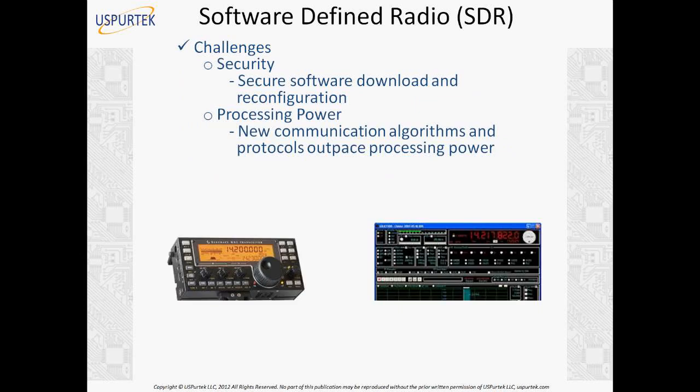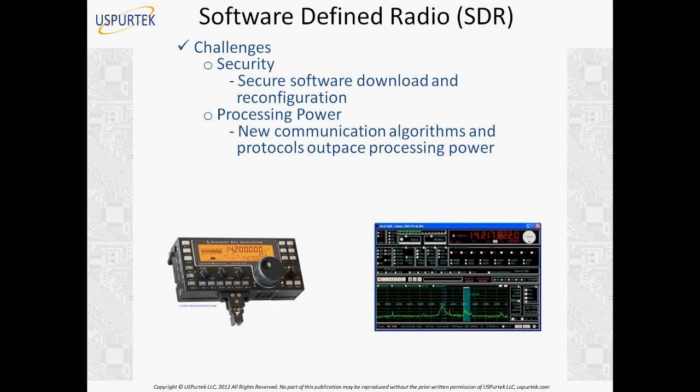Processing power. As we said before, new algorithms or new protocols can outpace processing power. So 5 years from now, you have a new version of the LTE standard. That means the current hardware, the 5-year-old hardware, may not be enough. You need more capacity, more bang for the buck. Despite these two challenges, SDR is going to stay. This is the future. Many vendors already have plans to put more and more software-defined radio in their base stations and in their handsets.